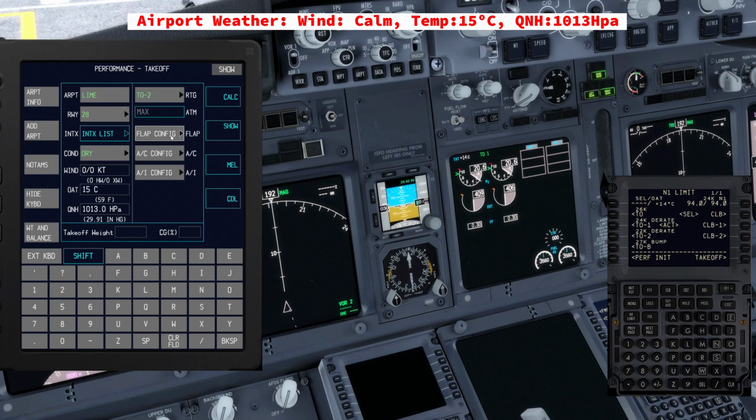So when we use the assumed temperature method together with fixed derate thrust settings, the 26, 24, 22, we actually combine them, and we are trying to get the exact takeoff thrust that we need. Because again, let's think about the example before. If you have a takeoff weight that requires a takeoff thrust that is between 22 and 24, you can reach that by using a 24K, as we said before, but with an assumed temperature. And that's gonna give you the exact takeoff thrust that you need for that exact weight.